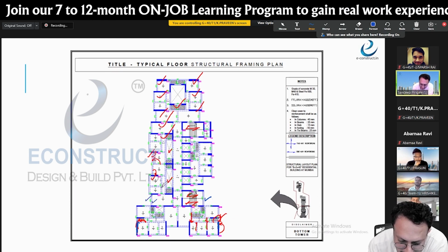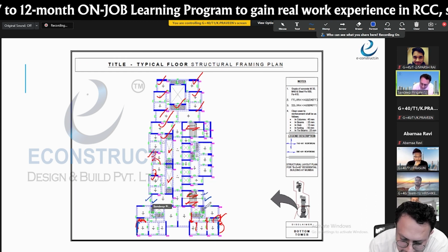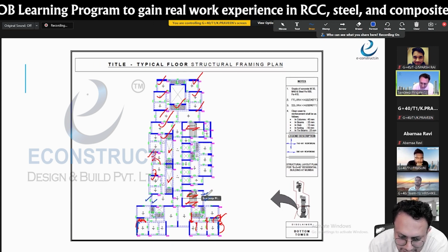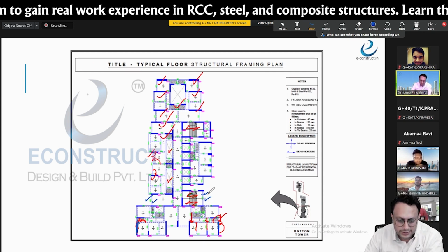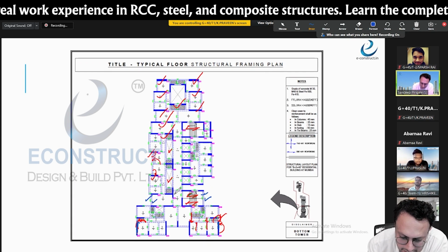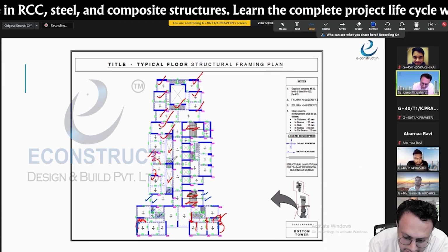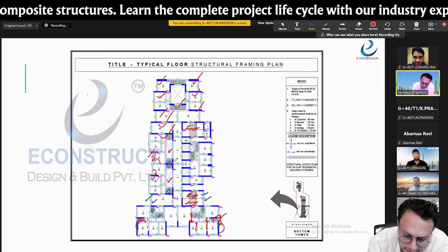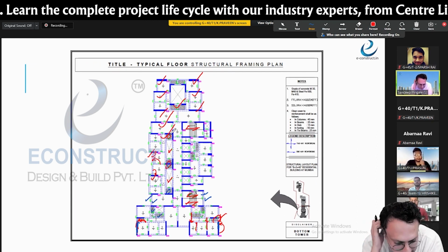Dotted line inside, this sharp line outside, both here also you need to see that are you going to give this as a floor beam? If the floor beam is there, yes, both the lines will be coming as a straight line. Since it's a sunken slab, here you are giving the one way, here it is missing. Correct, please add that. One way, two way markup is missing. Correct, no? Yes, sir. Yes.